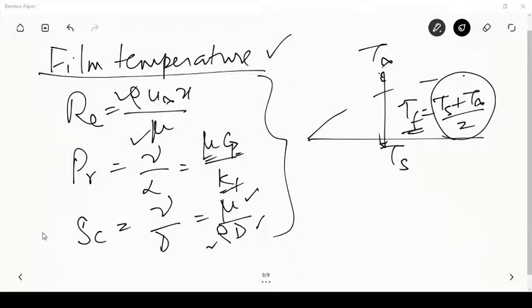Okay, so let's take a quick stock of what we did today. Today we first understood the Colburn analogy, in which we say that even for Prandtl number greater than 1, or rather greater than 0.6, we have a method of analogy where we write the j factors, jh and jm, which are nothing but the Stanton number times Prandtl to the power of 2 by 3, instead of Nu by Re or Sh by Re itself. So Cf by 2 is equal to jh or jm in the case of the Chilton-Colburn analogy, and this makes it possible to generalize the fluid flow results to get the heat transfer and mass transfer results even at Prandtl numbers deviating from 1. So that is the first thing we saw.